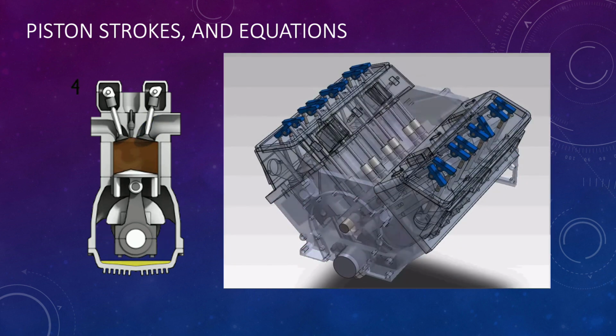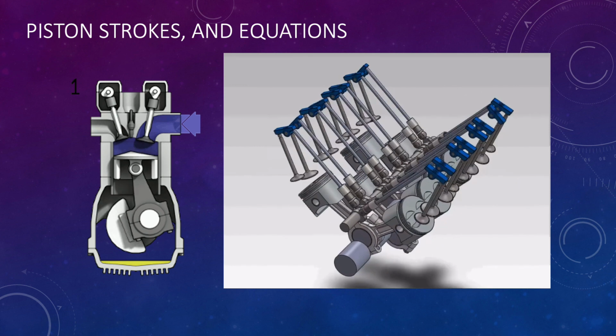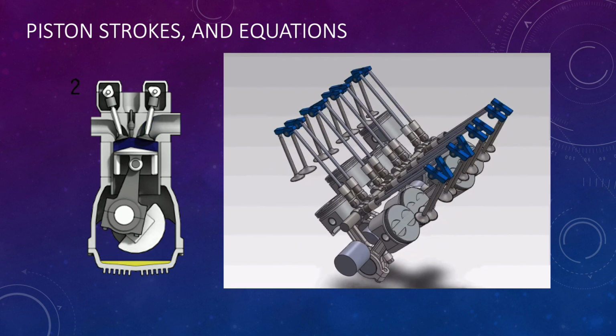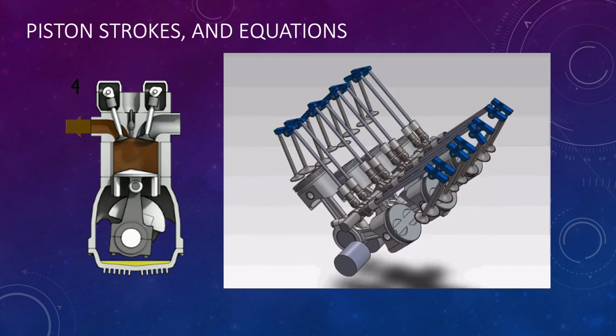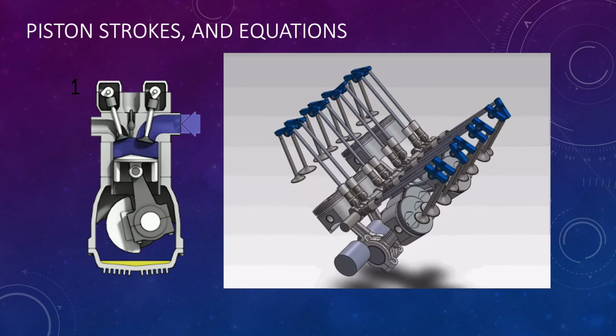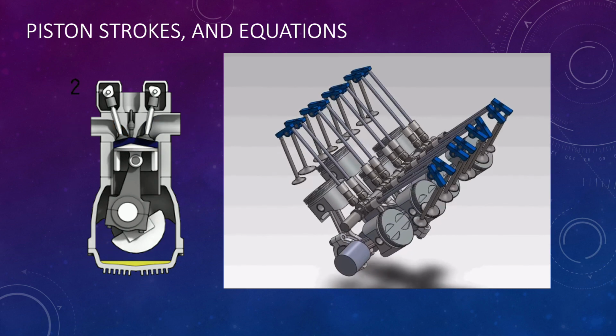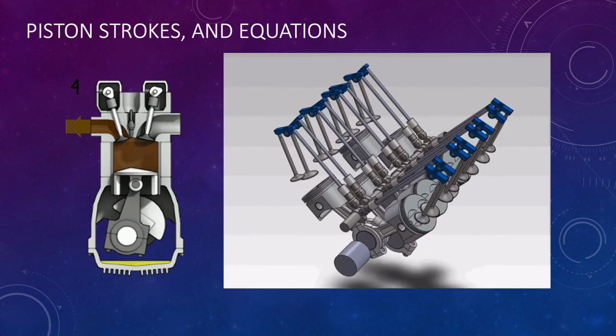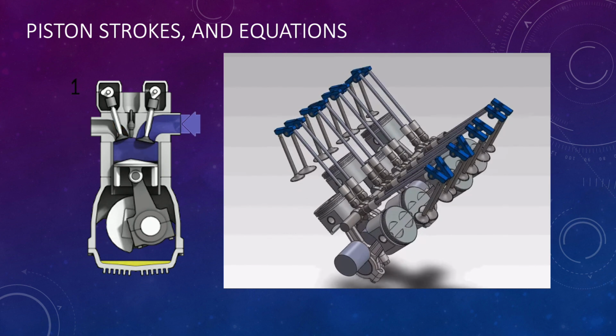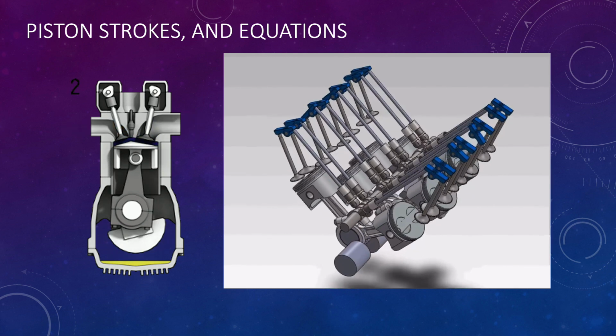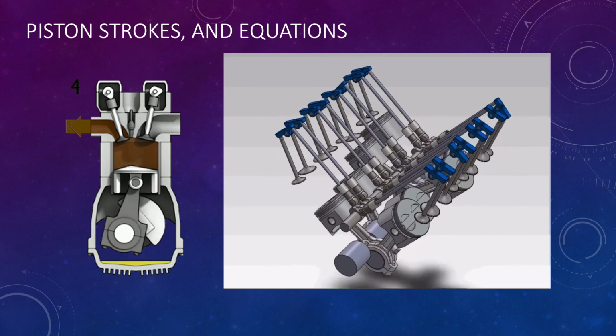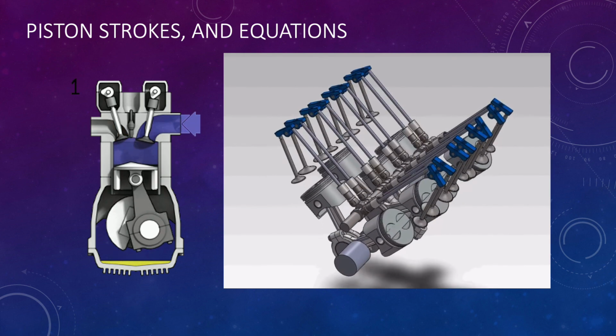As we can see from this video of a Chevrolet 350 engine, the pistons in an engine have their strokes occur at different times in order to compensate for outer moments, minimize internal moments, and therefore reduce the amount of vibration and bearing stresses. Counterweights on the crankshaft serve this same purpose.